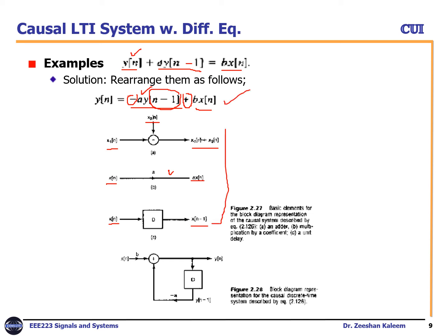So let's implement this equation now. For x[n] you have a b here, so multiply by b to get b x[n] at the input, and from the output, called y[n], when you pass it through a delay, you get a one-unit time delay, y[n-1]. For the delayed term you need a coefficient, which is minus a, so minus a y[n-1] comes here to the adder block, that is, addition.